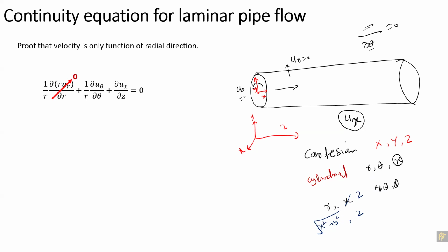But if you shift to the cylindrical system, r and theta, you will only be dealing with the r and the axial. It means that now you have simplified the problem to only 2 dimensions. So from a 3-dimensional problem, this is a 2-dimensional problem that will be solved in this way. So you take one plane from the axis like this. If you want to solve this problem as 2-dimensional in Fluent, then you have to use this plane from the axis, not up to the bottom.